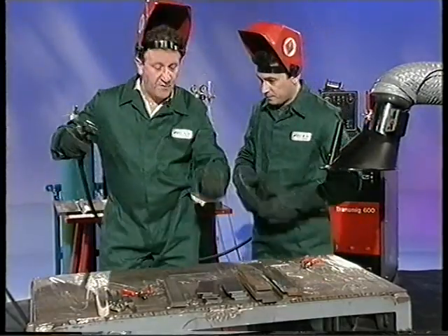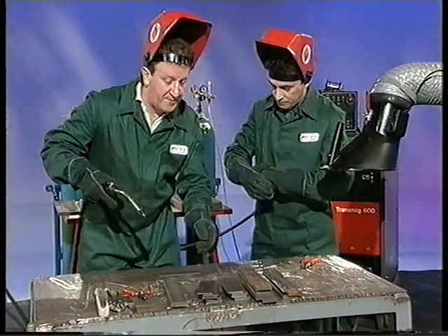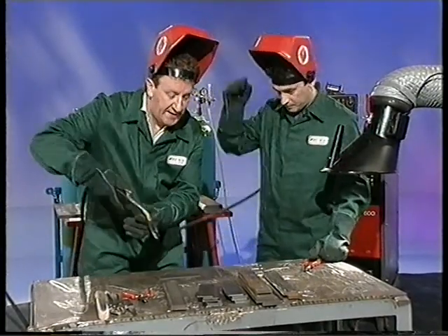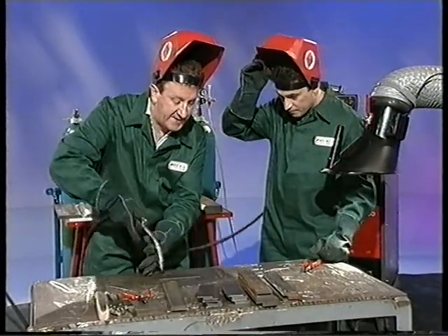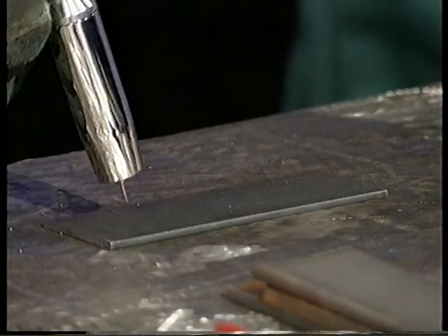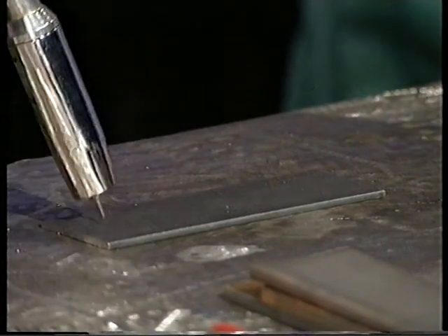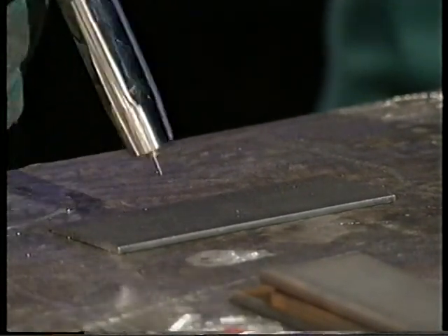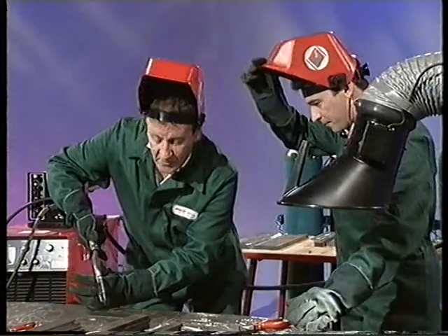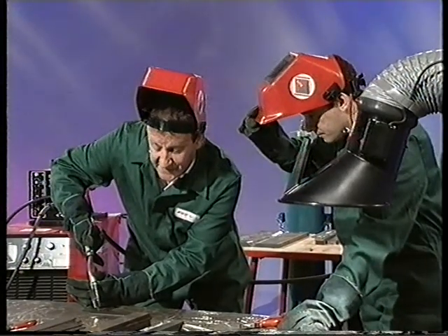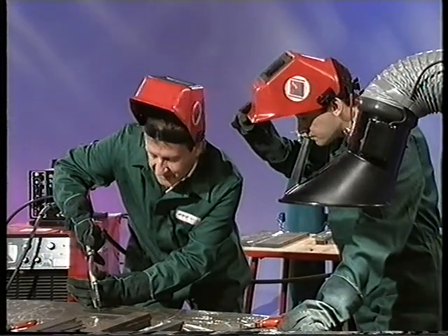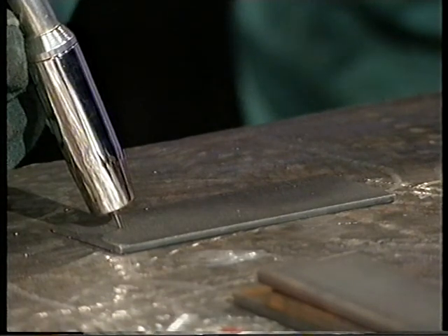The angles to be held for, in this case, this bead on plate, which is similar to a butt weld, are that in this plane, the torch must be directly overhead. But you have about a 15 or 20 degree lead on the torch from this vertical position so that you can observe the weld and see what's happening. Right. Stick out on dip transfer at this sort of amperage will be around 10mm. Mind your eyes.